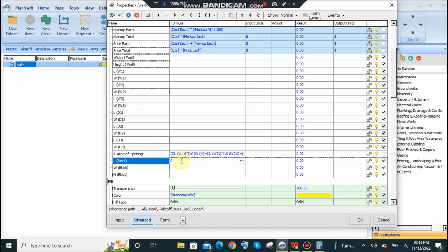If I tell the software that this is the standard length of block, this is the standard width of block and this is the standard height of block, then it will remember these values and show them when we start our command. Of course it will be a time saving process for us. This is for the case when you don't want to manually put values every time, and you can still put a value here like this, and this value can be easily changed every time, but these values will be there already for you, for your time saving actually.